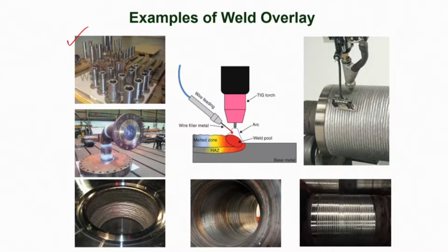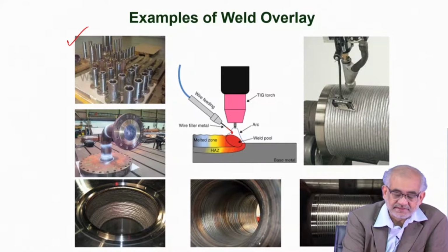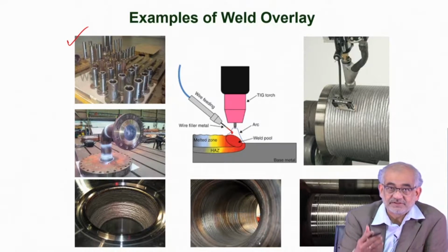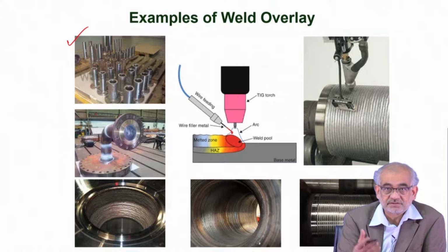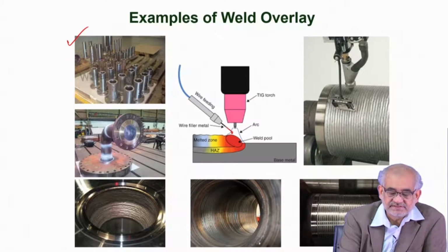Particularly in a situation where you have such a bent tube carrying say petroleum or slurry or say coal in coal washery or in other places, the inside of the tube gets immensely damaged, and you need to restore them by using a process by which you can create a beam which restores over the entire inside diameter, and every time you finish one circle, you move up or move down by a certain amount.